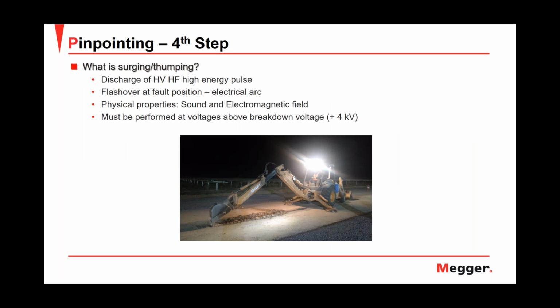So what is surging? What is thumping? What will I do when I thump my cable? I will discharge a high voltage, high frequency, high energy pulse, and I will flash over at the fault position. I will make an electrical arc when I thump the fault.